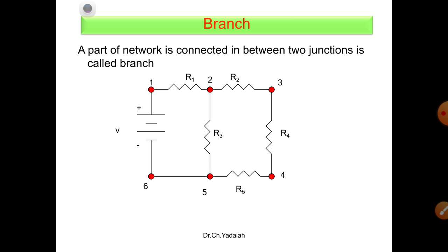Node 1 is connected to the voltage source and one terminal of a resistor, and node 2 is connected to resistor 1, resistor 2 and resistor 3, and resistor 3 is also connected to resistor 2 and resistor 4. Okay, so not 6 nodes, because some are common. So only 5 nodes are present in the circuit.